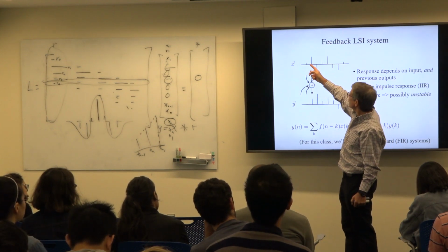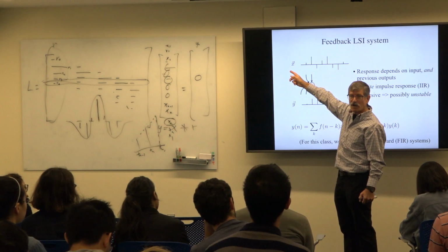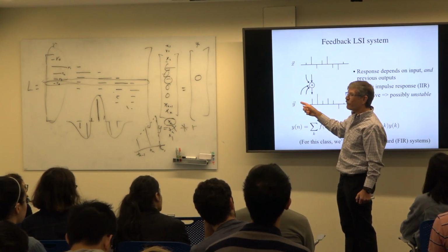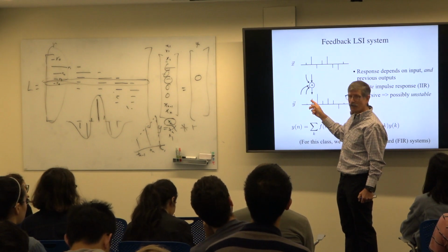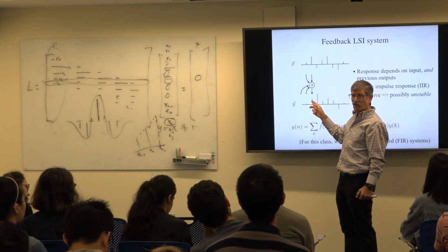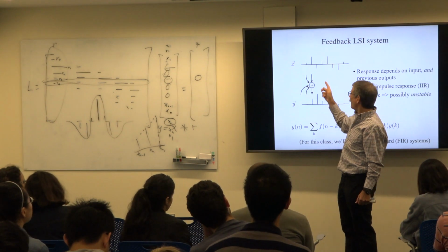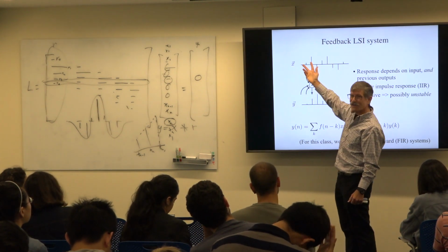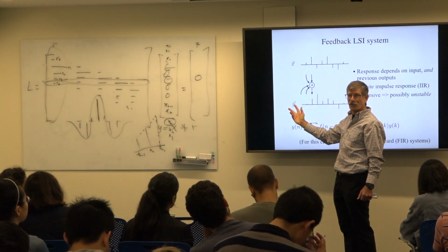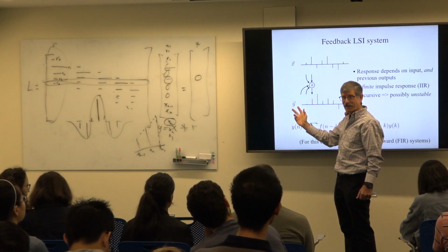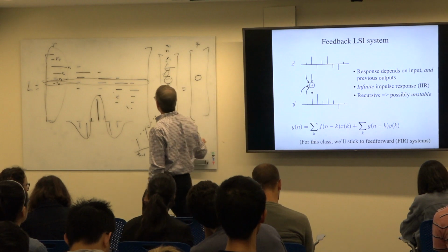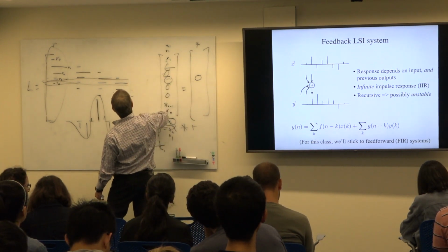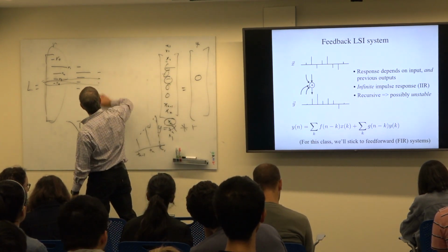But not just a weighted sum of past and current inputs, but also a weighted sum of past outputs. That's an extension. We're not putting this in a matrix anymore where all that comes in is x, because now here's a dot product, but part of the dots are with x and part of the dots are with past y's. I'm just going to talk about that for a brief moment, because it's a standard and useful thing, and you may even run into it at some point.